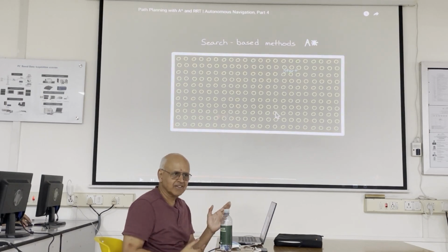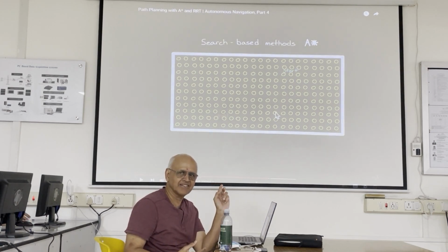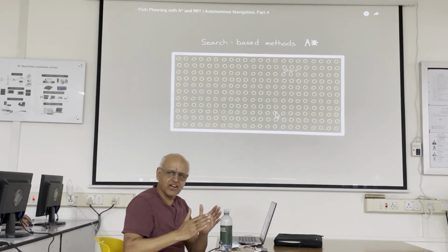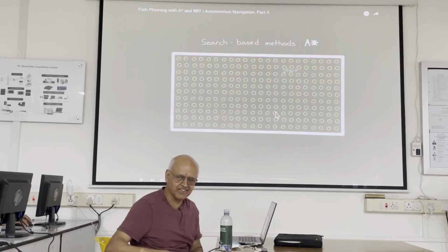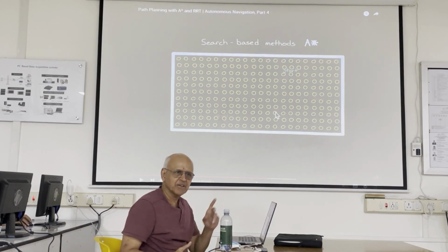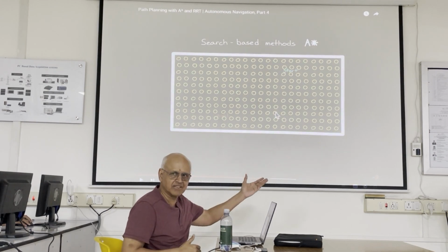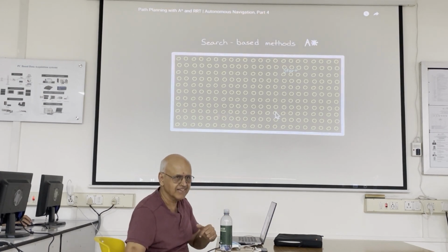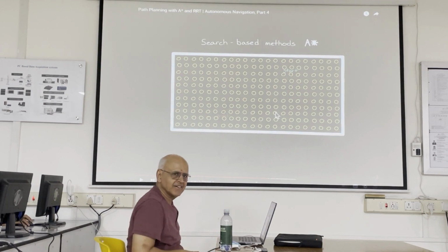For robots, it's x, y, theta, right? It's not even theta because the A* ignores theta. If you want theta included, then remember the first video I showed you today where he's taking into account a regular car. So then the dimension becomes 3 in planar space. If it's a drone, it becomes 6. 6 is still controllable, right? But when you have those manipulators, you can have like 12-degree space, and they still use A* to figure out the best path. The path is now this, right? Go underneath the table and pick up something and put it here, kind of thing. That's the path now.